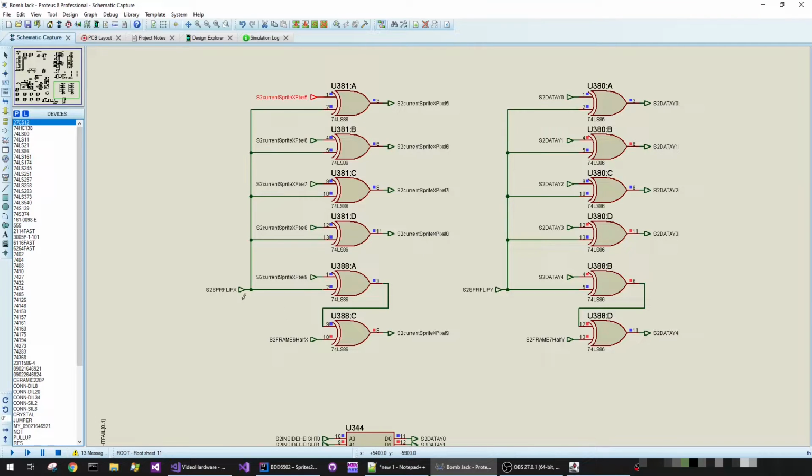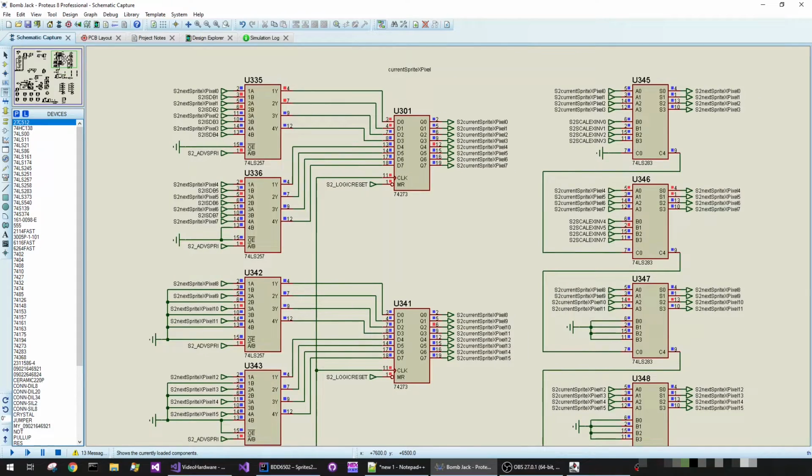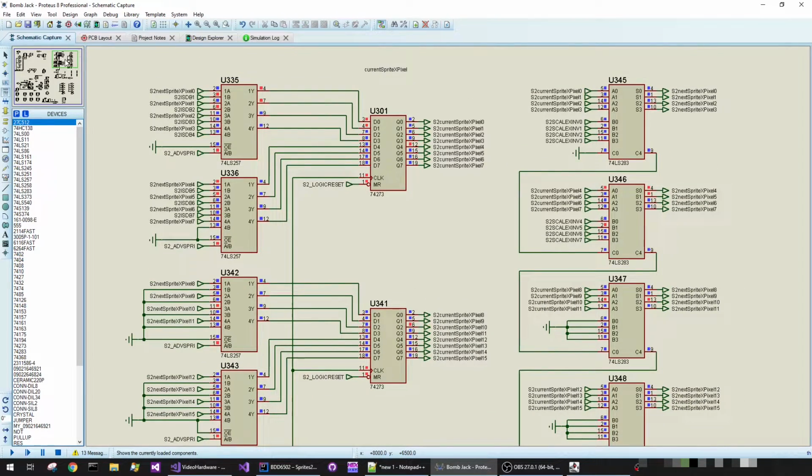It's dividing by 32. So this signal selection here is a great example of how the hardware can very easily do the selection based on the shift value. And because the shift value is constant, it doesn't need to jiggle about with all the signal values. Anyway, this does the flipping, so the flip X goes into the XORs and the flip Y goes into the XORs for the Y position, and all it does is a bitwise conversion here. So this logic here handles the current sprite X pixel, but with the 5 bits of accuracy baked in.